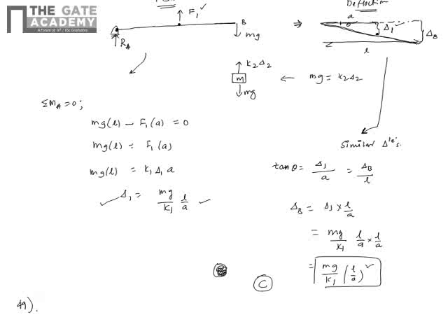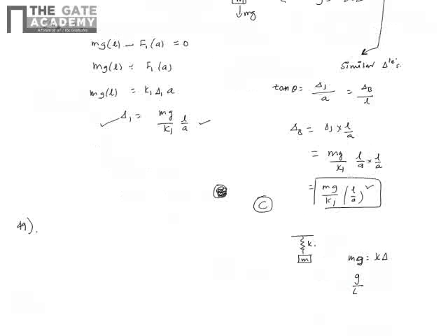Now for this, there is one thing which I need to tell you. Say if you have only a spring and a mass M, we can write at the static equilibrium that mg is k delta. So in this form, g by delta is k by m, where k is my spring stiffness and m is my mass, and this in fact is my omega square, the square of the natural frequency. So if I can bring anything in this form, this will be my equivalent stiffness and this will be my mass, and I can get the omega square.